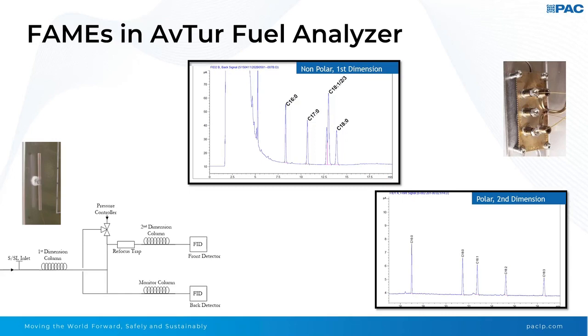minute. And as you can see from the first graph, the first dimension column gas is the cold eluted peaks. So it has to be re-injected into the second dimension column to improve the separation so that all of them are thoroughly separated. And you may also find that the C17 peak has disappeared in the second dimension column because it is not the target of interest and it has been cut off so that you will not see it in